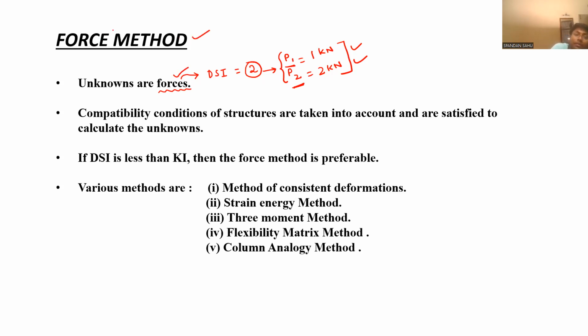In displacement method, the displacements are unknown, that may be rotation or deformation. In force method, the unknown may be a force or the unknown may be a moment. So these two you can take as redundant and analyze the complete structure using force method. So here the unknowns are forces, that is step 1.